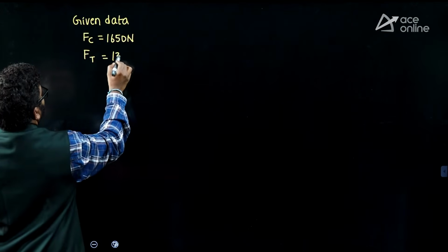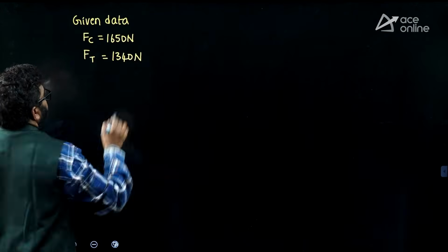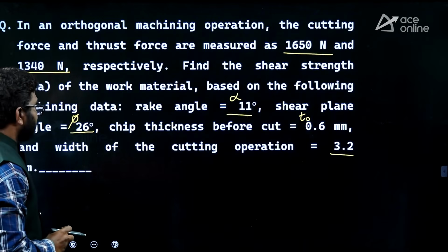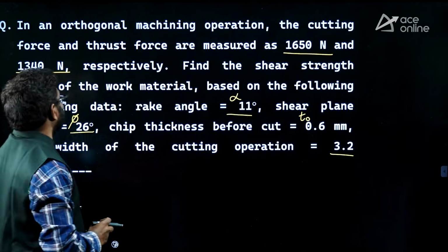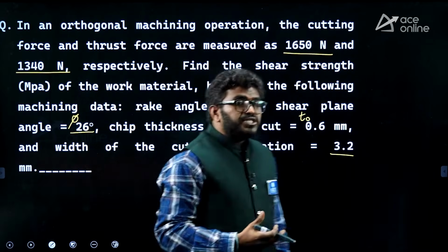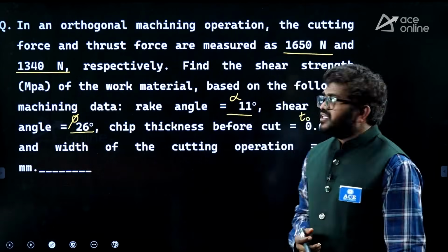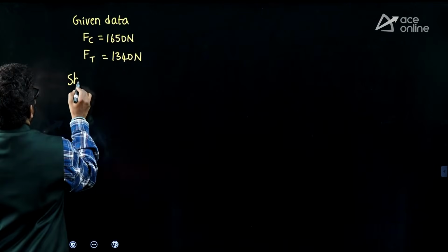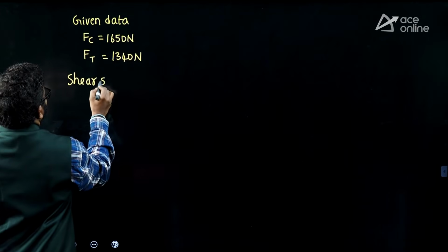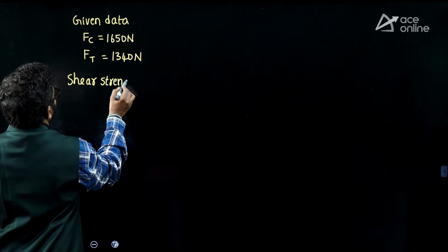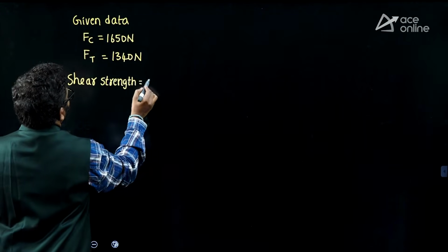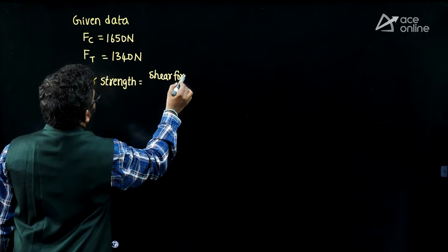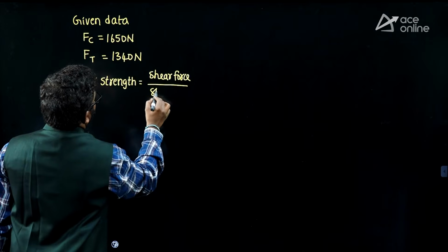They are asking the shear strength of the material in megapascal. So, how will you get shear strength actually? Shear strength is equal to shear force by sheared area.